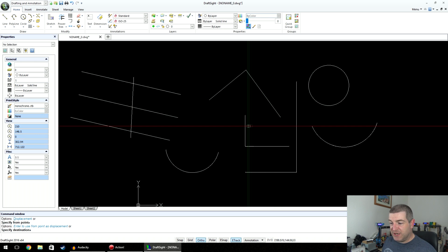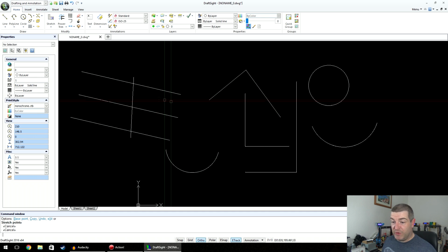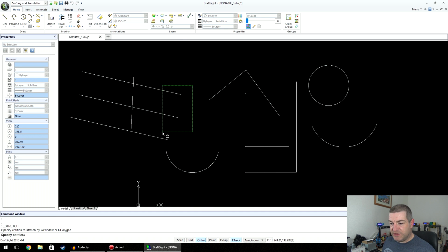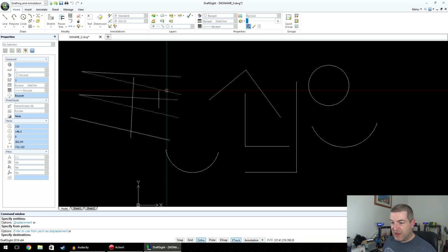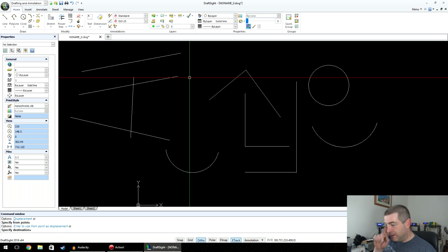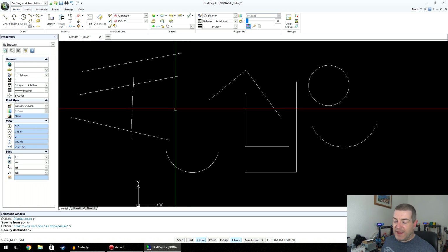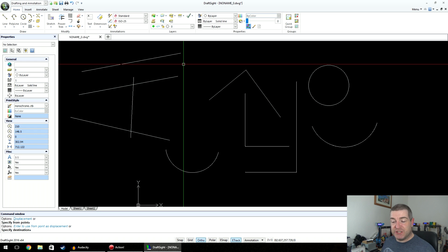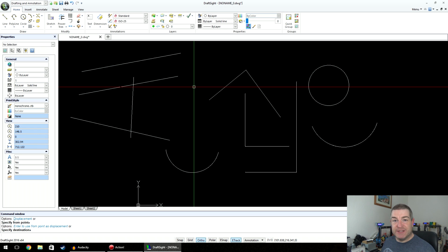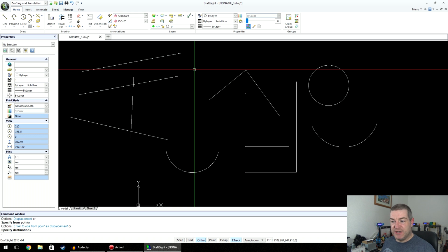When you do it on a single line, it's absolutely no different to just hitting that blue point. But when you do it on multiple lines, like we can do over here, so let's do it again. Stretch those 2 lines from there, and we can move them up. And as you can see, everything moves with it. It's really good for resizing rectangles and stuff. But that's the stretch command. There's nothing else that it does. It kind of moves the points at one end of a line.